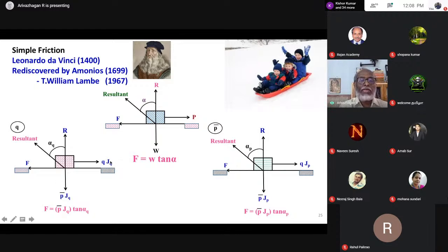This becomes non-dimensional. Some particles, as I already told, are affected by Q alone, some particles are affected by P alone. Therefore, I consider that particle alone in this case, JP, JQ, here JP. That means the area of the particle affected by Q alone. That is the area of the particle affected by the effective stress alone, P alone. Therefore, it's a constant. That's a non-dimensional number.